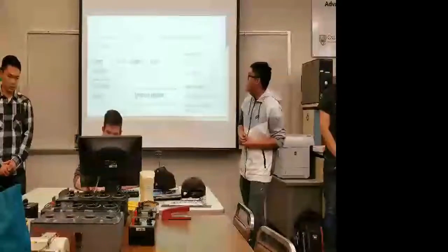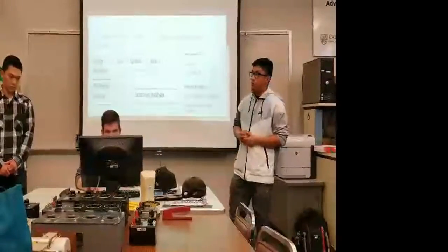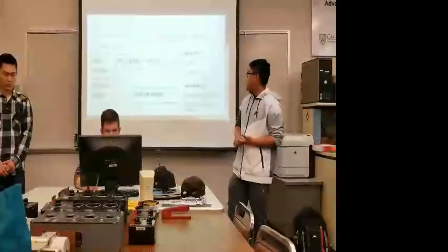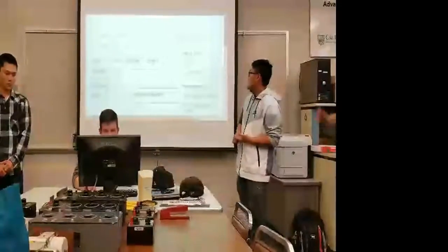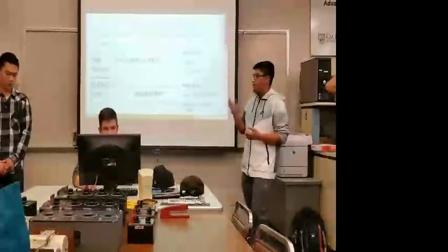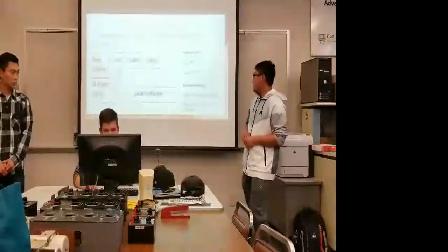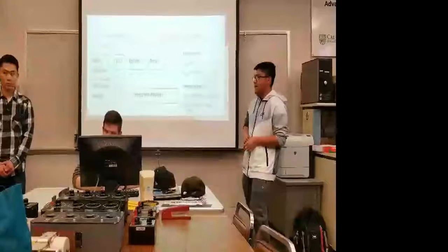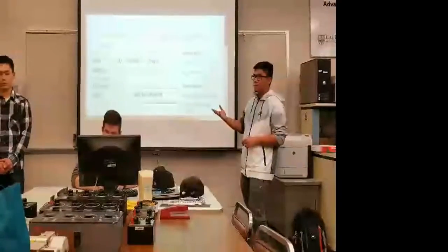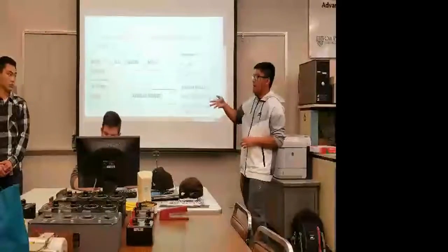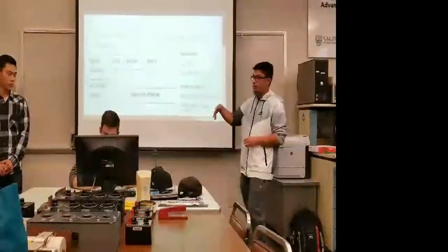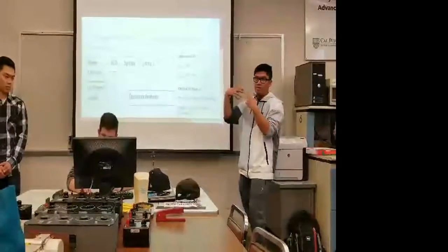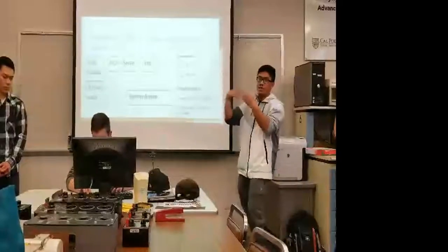So here's subsystem test 1. Here we're testing the power output coming from our second amplifier from the splitter. And as you can see, most of the data seen is going to be fairly similar to all those other subsystem tests, and what we figured out is that the amplifier is not amplifying enough gain in order to really have that output port from the splitter detect any signal or reflection coming off of the antenna.